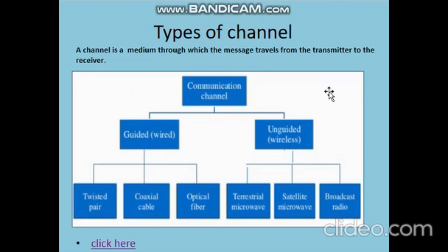The communication between the transmitting antenna and the receiving antenna takes place by different propagation techniques of the EM wave, like ground wave propagation, sky wave propagation, and space wave propagation. RF microwave links are point-to-point RF links between a transmitting antenna and the receiving antenna.